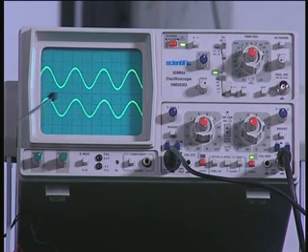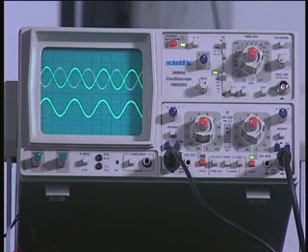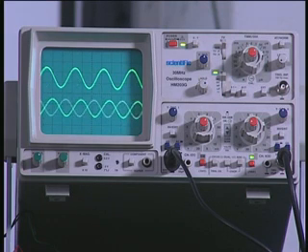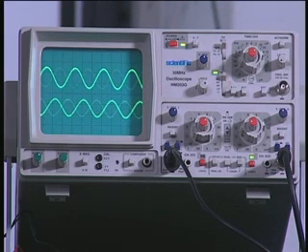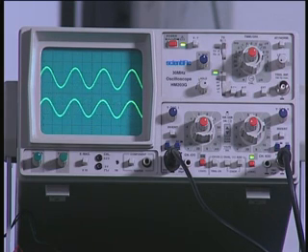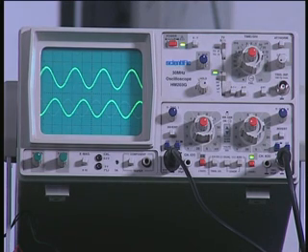Now, I want you to continue to observe the oscilloscope while I change the potentiometer, and you would find the trace slowly moving away. Right now, we can see that the trace starts moving to the right, and then I can go almost up to the 180 degree phase shift. Then I come back now, the potentiometer, now it is in phase. Now, as I move that, you find it is shifted towards the right, and therefore, the phase can be continuously varied from 0 to 180 degrees.